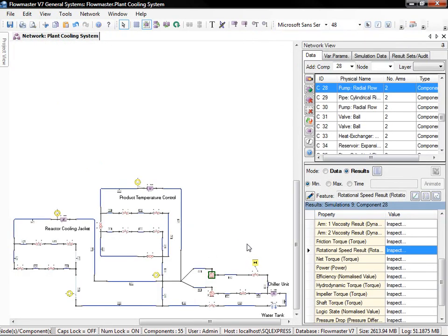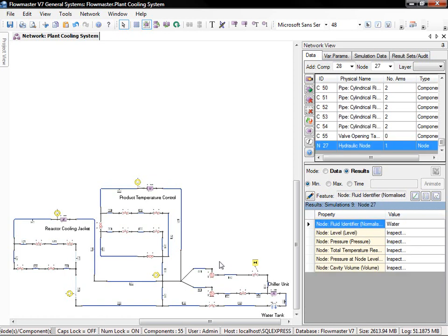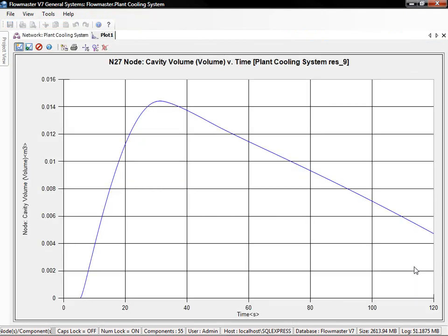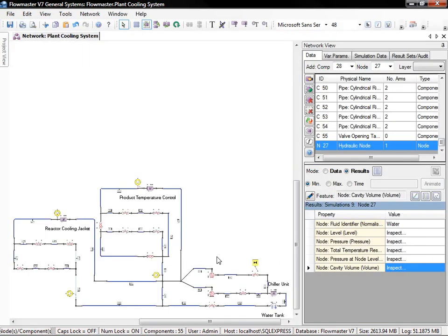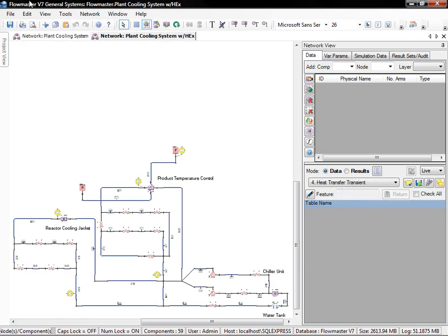Well, with a pump, anytime we shut it off, there's going to be a certain amount of inertia still going on in the system to make sure that the pump comes to a complete stop. If sections of the system are closed down too quickly, what we can get is a cavity that forms on the upstream side of the pump. As we can see here, we could then work on understanding how quickly and when we can close any sort of valves to prevent that.